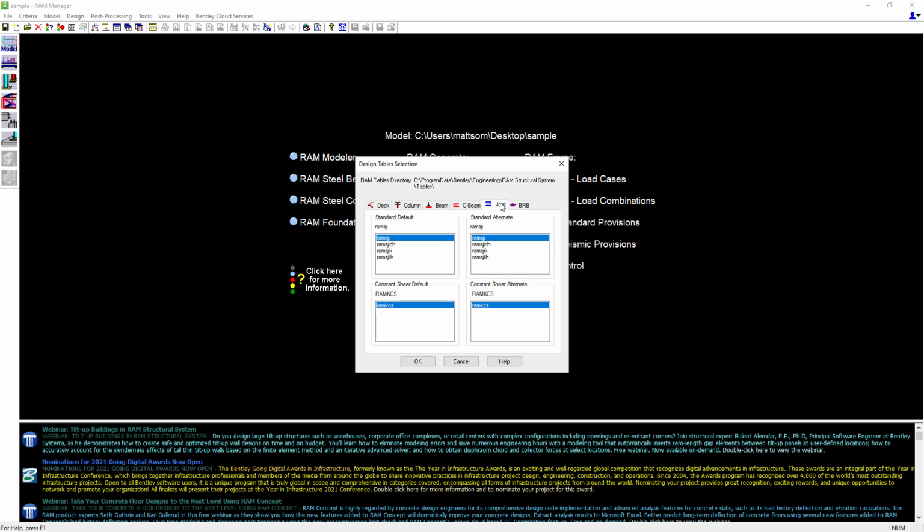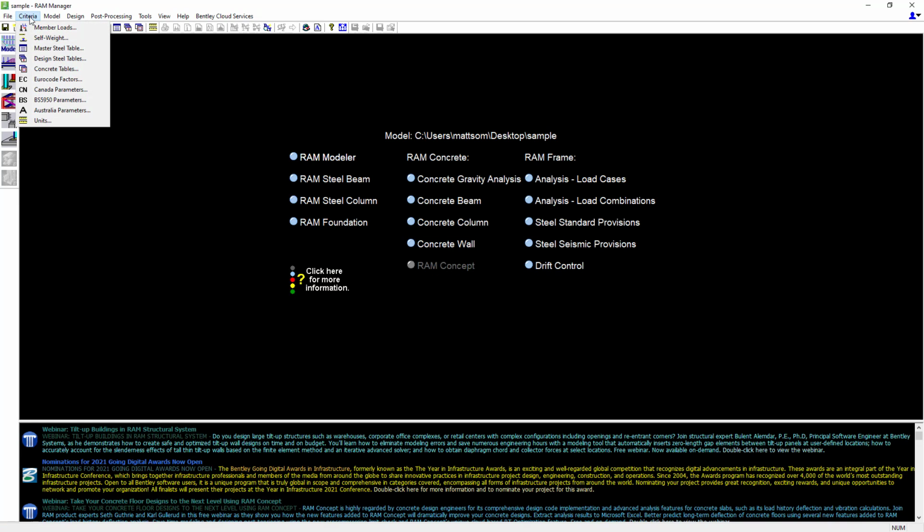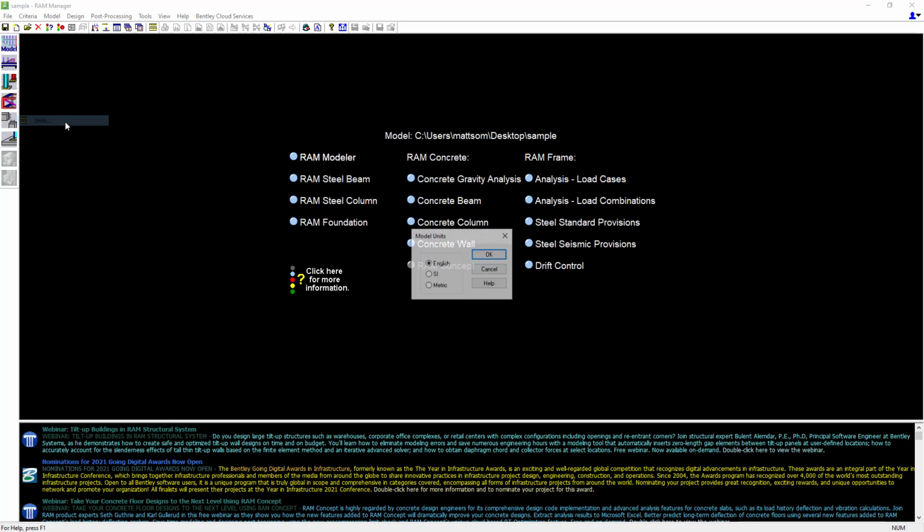I can change these depending on what part of the world I'm working in. Concrete tables. This video is not really going to deal with concrete. Eurocode, Canada, some of these other standards here we're not going to worry about. Units, I'm going to stay in English units for this video. And then once we have our criteria set, we want to come to our model.